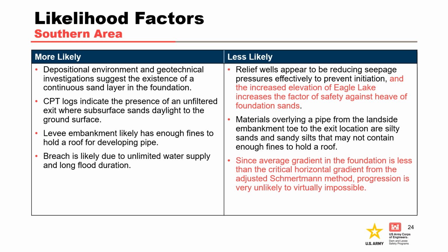In the southern area, the flood fighting efforts bolster two of the existing less likely factors related to BEP. The increased elevation of Eagle Lake increased the factor of safety against heave at the seepage exit location and reduced the average gradient in the foundation further below the critical horizontal gradient for progression of BEP. While perhaps less effective than in the northern area, the intervention efforts undertaken had an effect on the likelihood of BEP in the southern area.